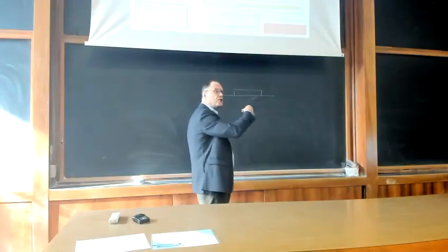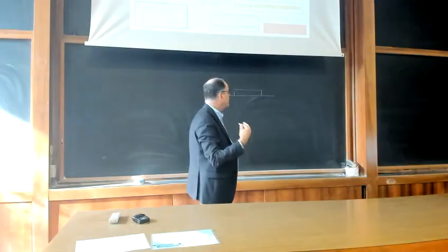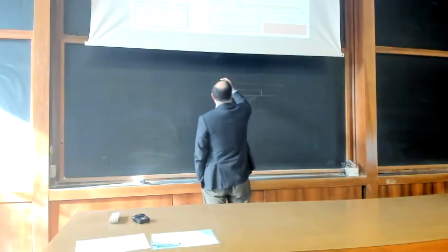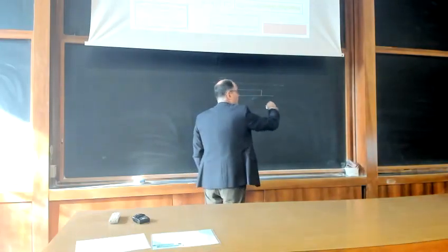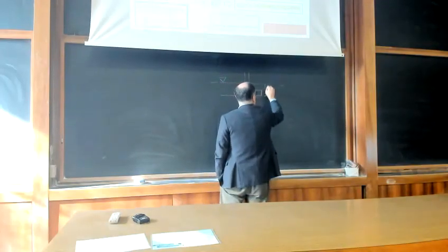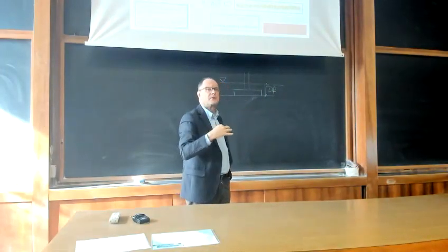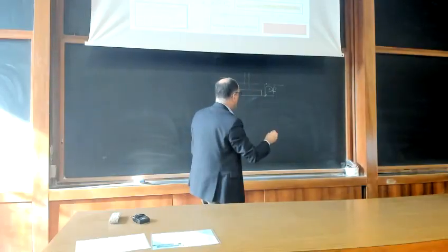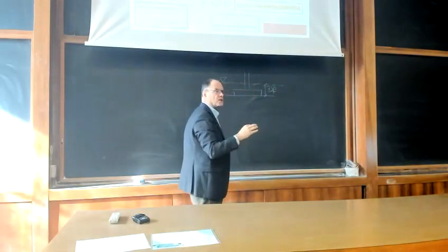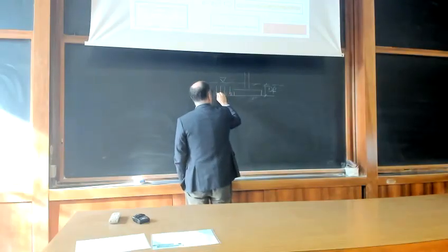Okay, so by Q limit, let's be certain that we understand, we have a footing like that, you see. In this case, the footing is considered placed on top. This is not necessarily the ground surface. Actually, we said that this is the ground surface, and your footing has to be placed at a certain depth, D or DF, what we call. Okay, so this is not exactly on top of the ground surface, but in our scheme we remove this soil, and we just consider the contribution in terms of surcharge loads.